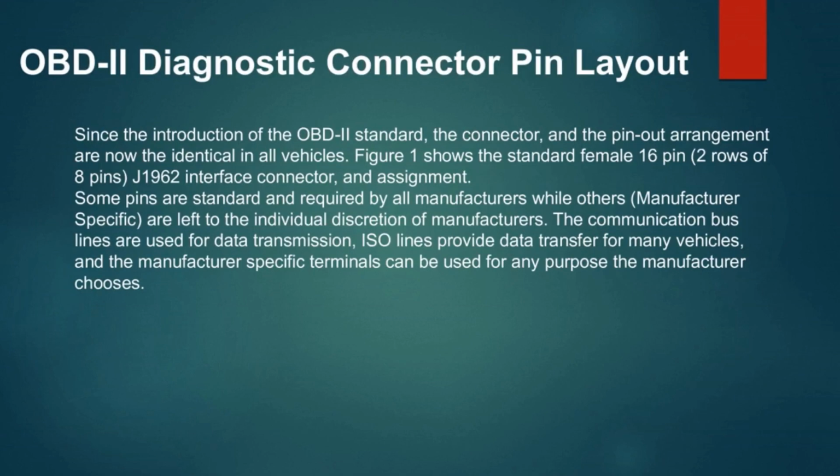OBD2 Diagnostic Connector Pin Layout. Since the introduction of the OBD2 standard, the connector and the pinout arrangement are now identical in all vehicles. Figure 1 shows the standard female 16-pin, 2 rows of 8 pins, J1962 interface connector, and assignment.